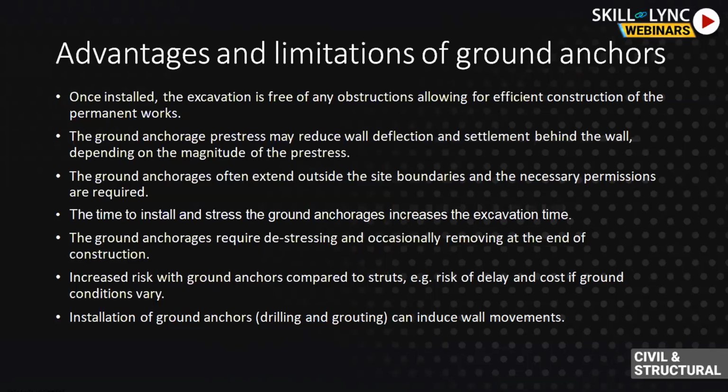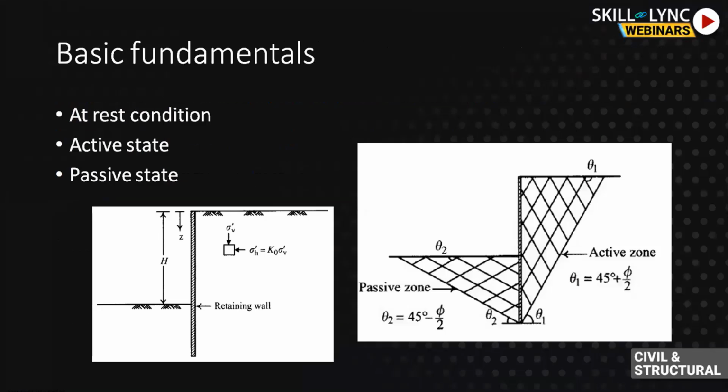So these prop systems are the main systems for excavation, and when it comes to deeper excavation, more than 8 meters, we have to go for either an anchor or strut arrangement. Next to this, we'll be looking at some basic fundamentals. For this construction, the basic is the earth pressure theories.